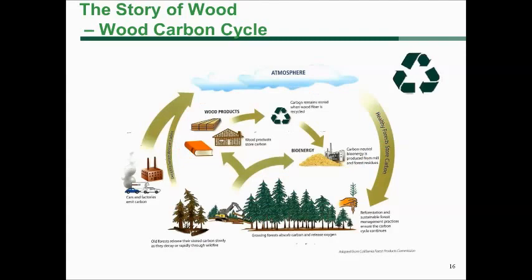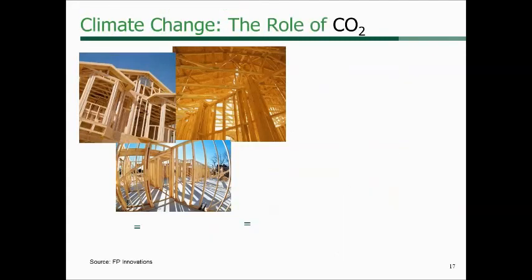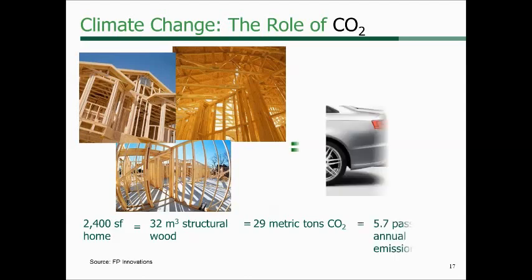And this is one of the main reasons that we're seeing more and more use of wood products throughout the world. Now, as an example, here's a wood building, and it could be your home. Many of us live in wood homes, and if we had a wood home that's 2,400 square feet, that is estimated as 32 cubic meters of structural wood, which equates to 29 metric tons of carbon dioxide, because wood is roughly 50% carbon. So for long-term storage, that is storing as much as 5.7 passengers' annual carbon dioxide emissions from a car.